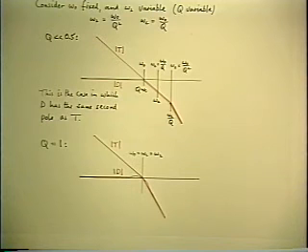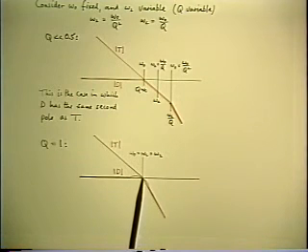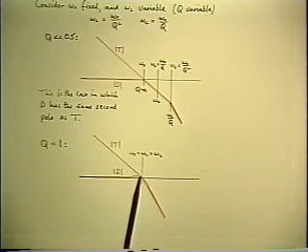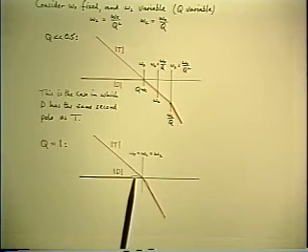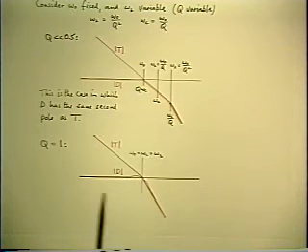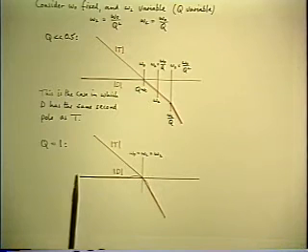What's the phase margin now? Yeah, about 45 degrees. Because at the crossover, again, you get 90 degrees from the initial slope, and you're right at the second corner, so the second pole is giving you another 45, so the total phase lag is 135, and the phase margin is 45. So now you associate a 45 degree phase margin with a closed loop response which is beginning to peak up.